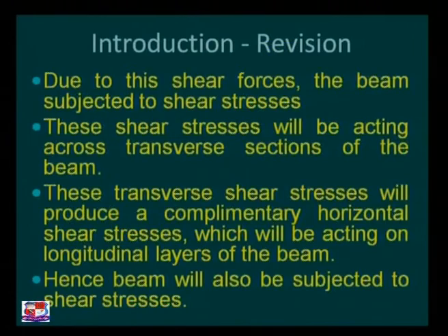These shear stresses act across transverse sections of the beam. These transverse shear stresses produce complementary horizontal shear stresses which act on longitudinal layers of the beam. Hence, the beam will also be subjected to horizontal shear stresses.